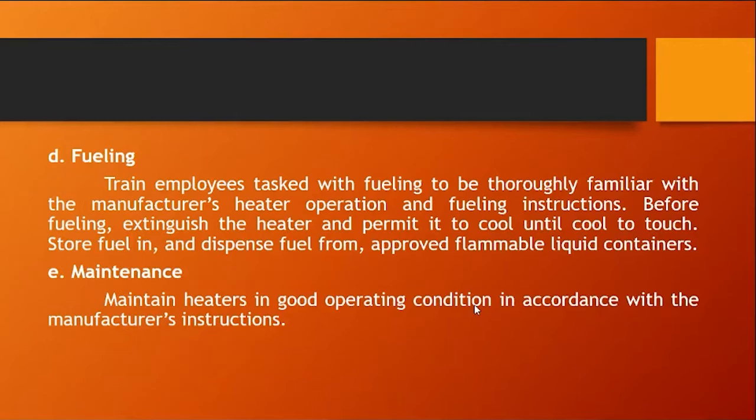Before fueling, extinguish the heater and permit it to cool until cool to touch. Store fuel in and dispense fuel from approved flammable liquid containers. For maintenance, maintain heaters in good operating condition in accordance with the manufacturer's instructions.